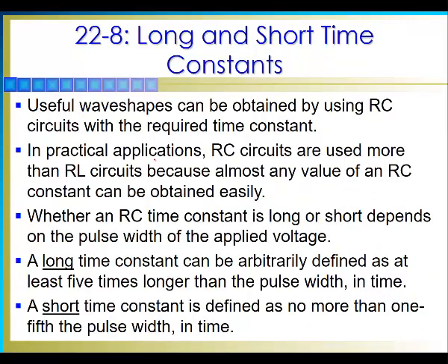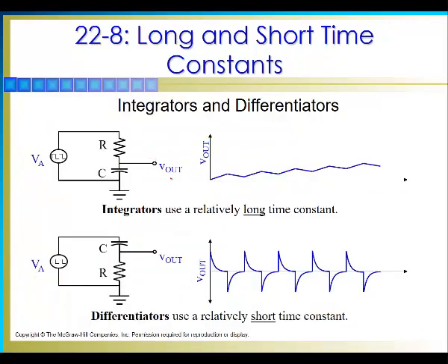And when we have a long time constant, let's say for example the time constant is very long, either because the capacitor is large or because the resistor is large, this will be the voltage on the capacitor. It will never get down to 63%, because from here it's not even a full time constant.